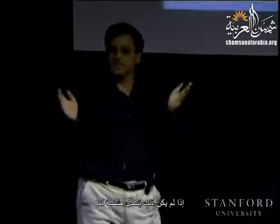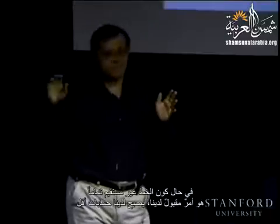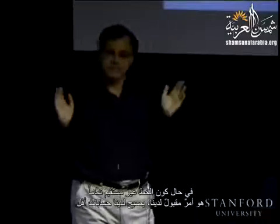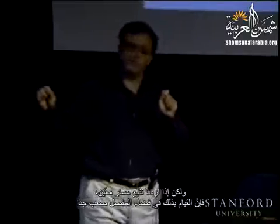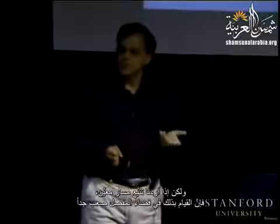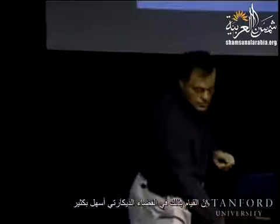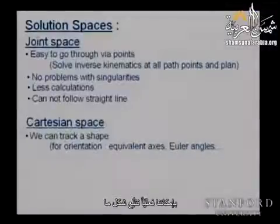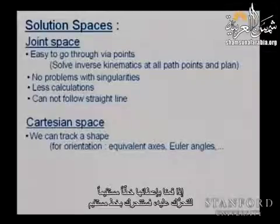If it is not a problem for us, if it is not exactly a straight line but it approximates it, that's fine. So we have fewer calculations. But if we want to follow a particular trajectory, doing it in joint space is very difficult. That's much easier to do in Cartesian space, right? We can actually track a shape because we're putting the points that we want to go through in the actual Cartesian space where the manipulator moves. If we give it a straight line to move on, it will move on a straight line, right?